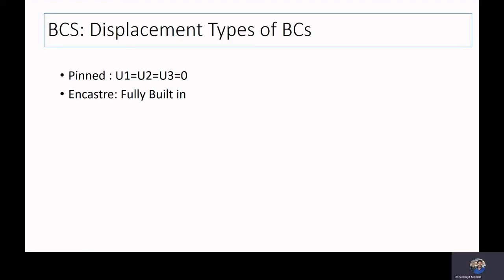Here we'll discuss the boundary conditions. So see, we have the cantilever beam, and we're modeling it using a shell element. As per the notation of ABAQUS, we have made this in the X and Y plane, and in this direction we have the loading, from the top. Now, the cantilever beam means one end is fixed, the other end is free.